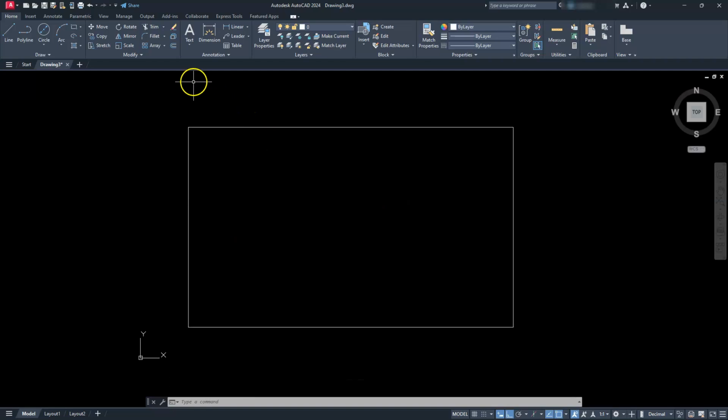The way that I'm going to do that is if I use the regular offset command, it's going to offset the entire rectangle. I don't want that to happen, so I have to do one or two steps. First step is I would have to explode this, right? So I can take this rectangle and then I can explode it. Or I can choose option B, which is use an offset command inside of the construction line.